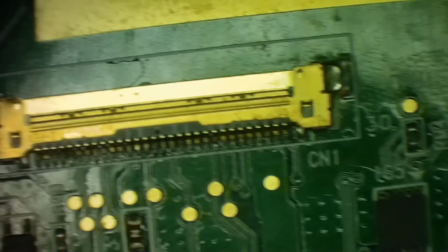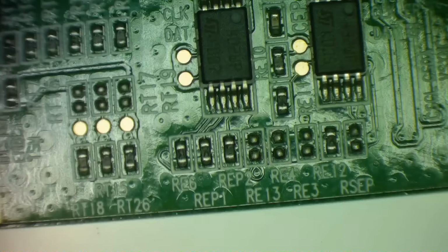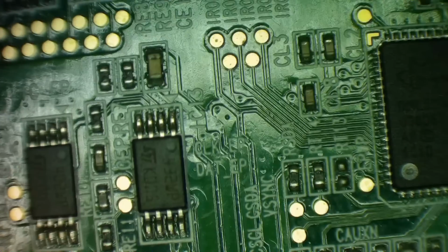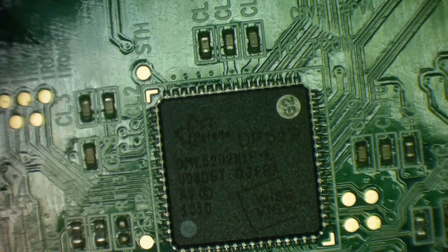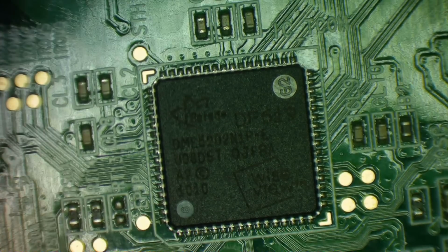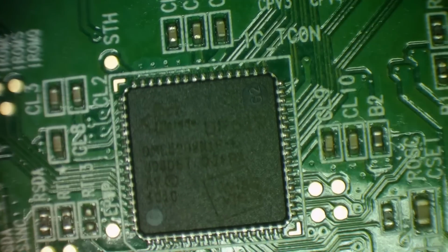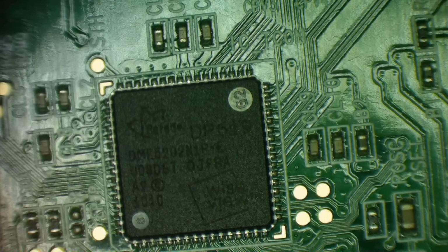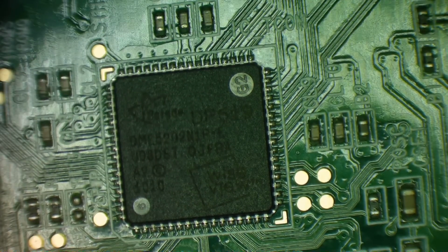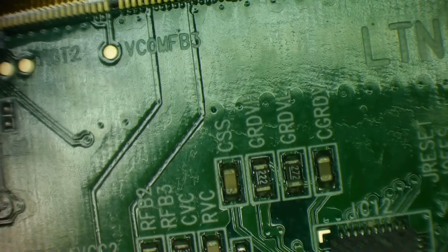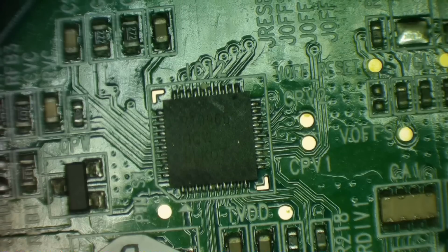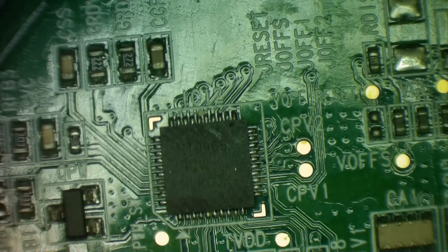But we have some chips on here, so let's have a look to see what's actually on the board, and maybe this will give us some indication as to what's wrong with one of them. This, I'm fairly sure, is going to be what's called a TCON. In fact, I think it even says IC TCON, timing controller. So this chip should be very much involved with generating the image. The one over here, this one, I suspect this is to do with the gamma correction. This basically sets a lot of voltages that control the brightness of the screen and control the image on the screen.